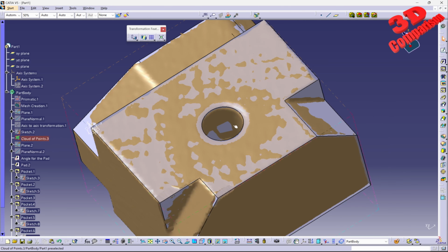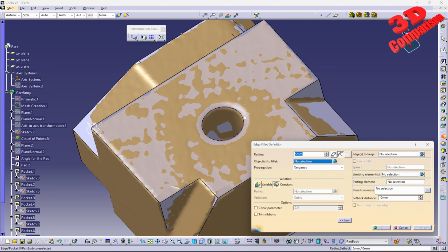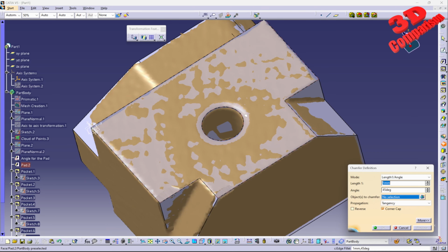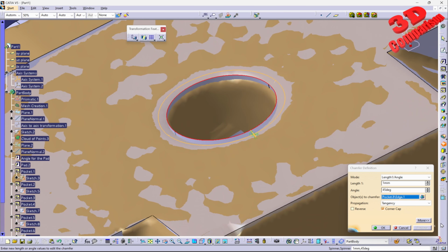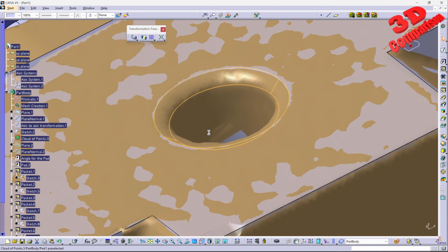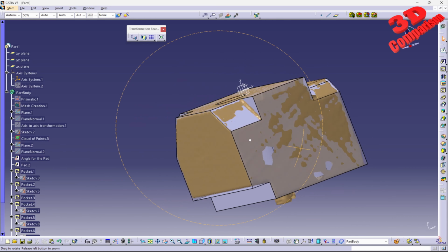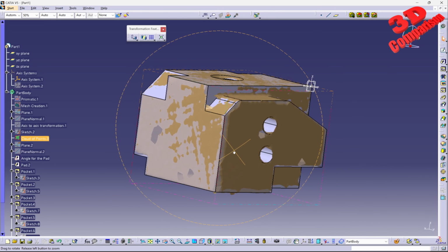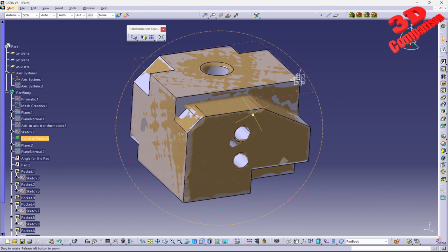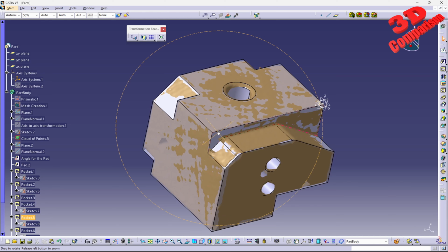And we also have one chamfer over here. So this will be fillet. I will go for chamfer. With 1 millimeter, it will be the following. So I will go with 1.5 in this case. And now I can hide the point cloud and I can check that model. And I can also do some analysis between those. So overall, this is the workflow that we can use to do some reverse engineering.